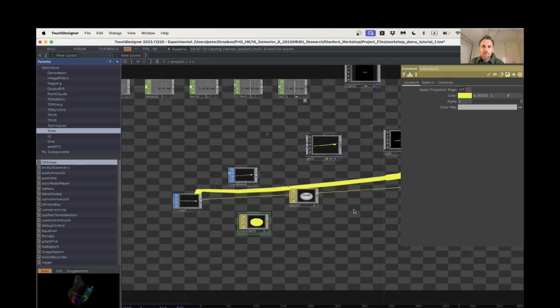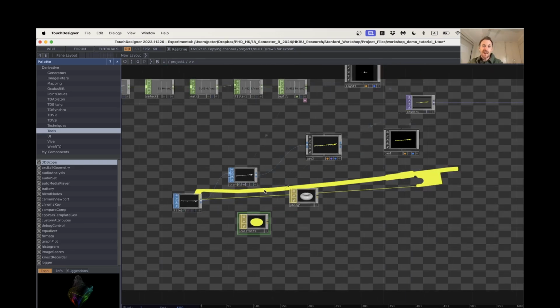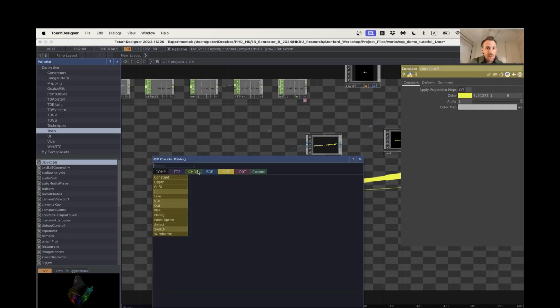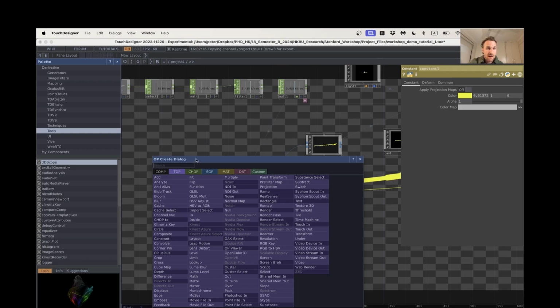Okay, it's made that violin bow a completely flat yellow. So constant means that it's not looking at the lighting information. It's basically emitting that color wherever the camera can see it with full luminosity. Whereas this one here, it will receive lighting. So on the constant, first of all, instead of that color there, we can add our texture map of the violin texture.